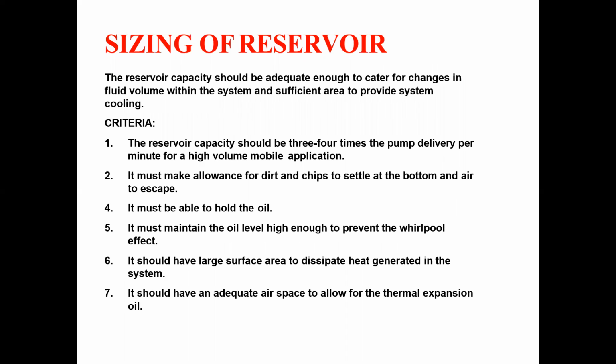Then here are the factors which we are going to consider during the sizing of the reservoir. All these factors were already discussed previously. There should be a sufficient quantity of oil present. It should provide air ventilation. An air vent should be provided there. It should maintain the oil level high enough to prevent the whirlpool effect. And it should have a large surface area to dissipate heat generated in the system. And it should have adequate airspace to allow for the thermal expansion of oil.